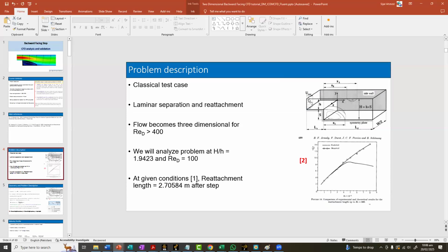Fluent also gives you an expression function, and tabular data you can also apply. If this is a simple case, you can even apply a simple table of velocities. You can take the equation into Excel, get the points for x and y, and apply that directly through a simple text file. Okay, but that we're not going to discuss. We're going to discuss the UDF.